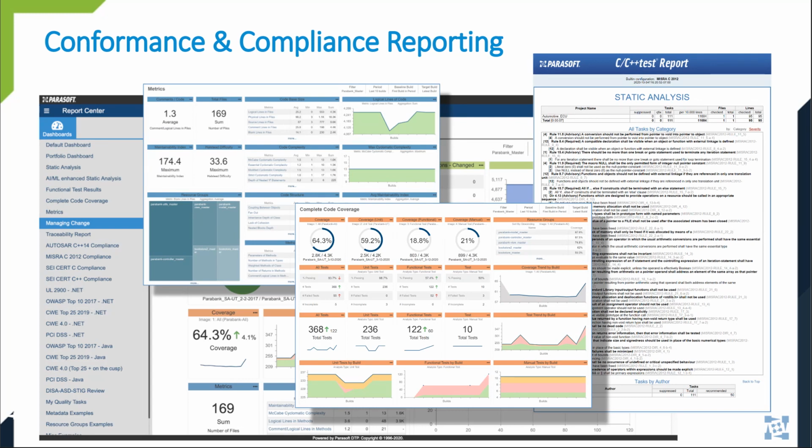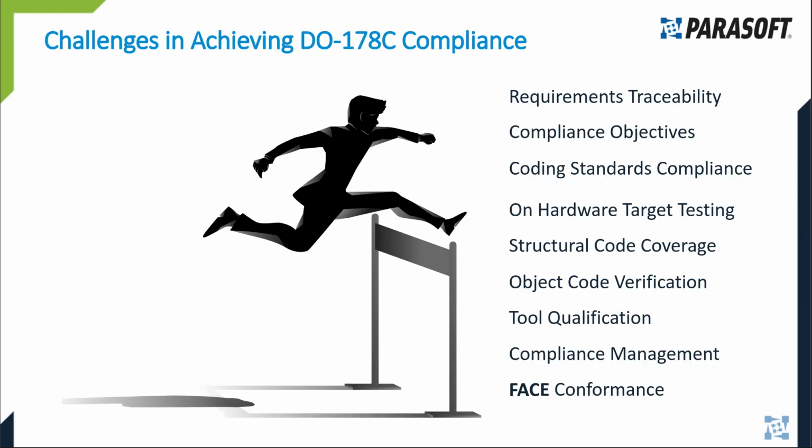In fact, this leads me to the next slide. As I previously mentioned, avionics software also has requirements from process standards like DO-178C or B, which are very different than, as you're probably now aware, the FACE standard requirements. Now, for DO-178, some of the key challenges are requirements traceability, managing compliance objectives, compliance to coding standards, on-target hardware validation testing, code coverage, including at the object level, and the tool used needs to be TÜV qualified.